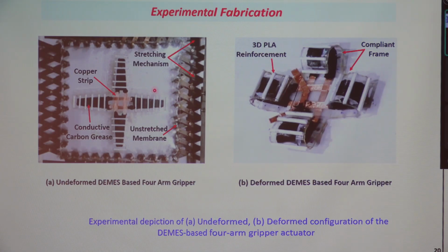But we have considered an initial pre-stretch of 2 in both directions. So it will bend the legs more, because more strain energy is being provided by the membrane to the legs. This is an initial attempt with a pre-stretch of 2, because we are anticipating that with a good pre-stretch of around 2, we will get good actuation. The leg will curl because we are providing a biaxial pre-stretch of 2, which is very high. Then we evolve: we take less pre-stretch or uniaxial pre-stretch, and we keep evolving until we find a very good gripping of that gripper. All that imagery I will share, but for basic understanding you can get it from here.